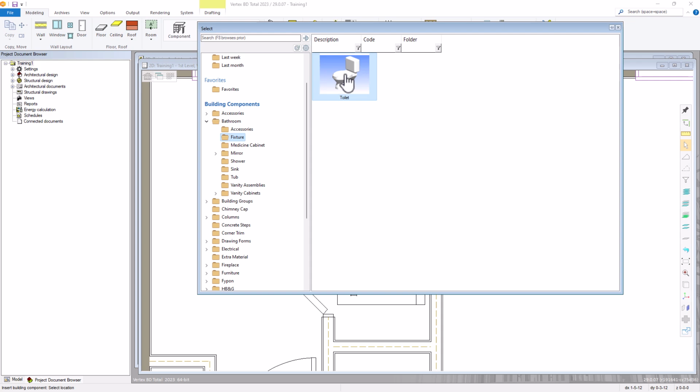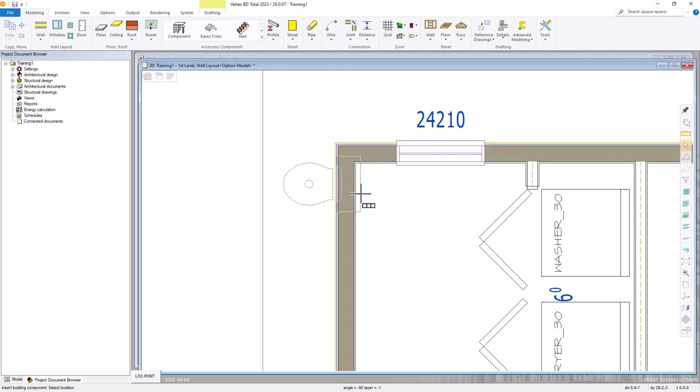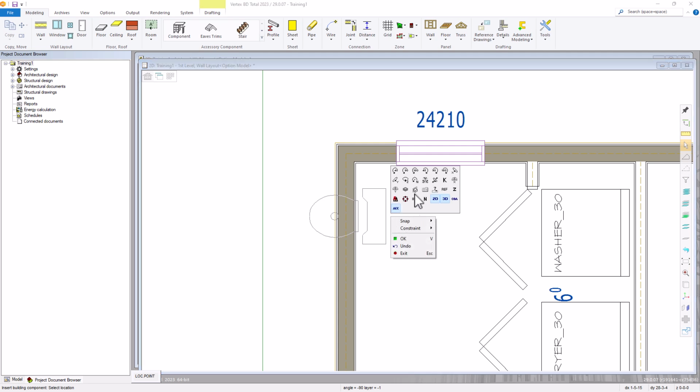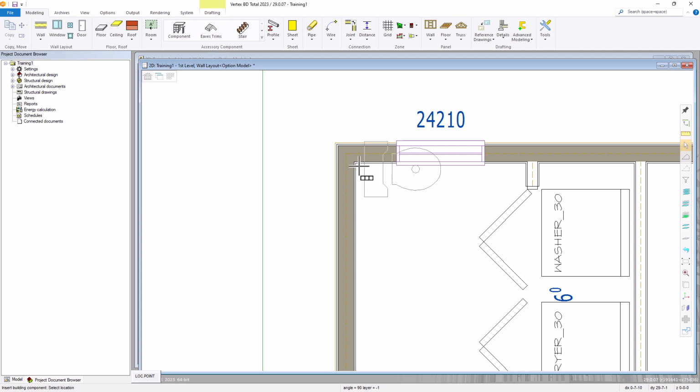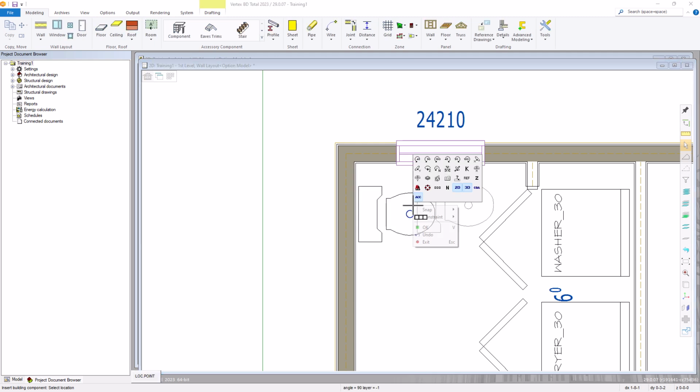So we'll double click that, zoom out, locate that off this wall, let's say about 18 inches. So we need to rotate this, rotate it 180, and it's centered there. So I'm just going to find that interior corner, get that yellow icon, hit Q, pull that down, lock it in the vertical. Actually, I need to hit the letter I, pull that down, type in 18, and V to confirm.